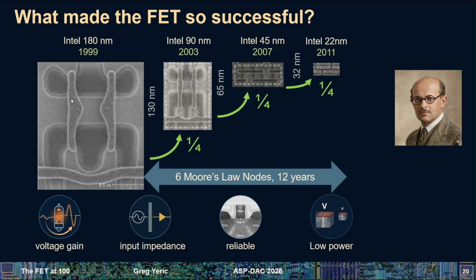Another fact is people versed in the art understand that when I'm showing these pictures, I'm talking about SRAM bit cells. This is an SRAM bit cell. SRAM, and we'll talk about this further in the course, uses 6 transistors to store a bit. And so the features on the top are the gate features, and then underneath them are the active regions, diffusion in the old days into silicon, and then isolation oxide is the field oxide. So wherever you have a gate crossing the diffusion, you've got a transistor.